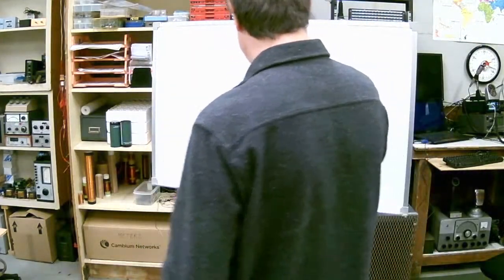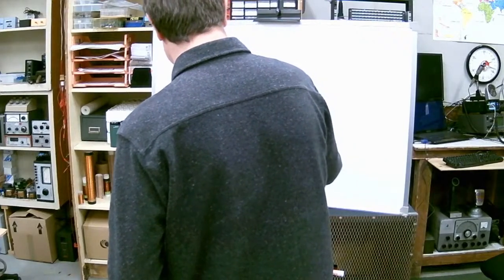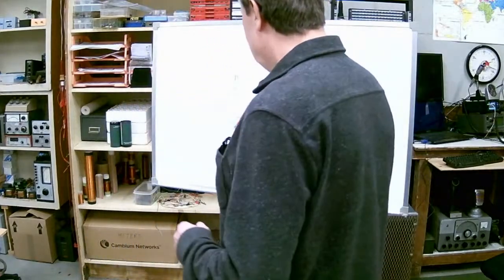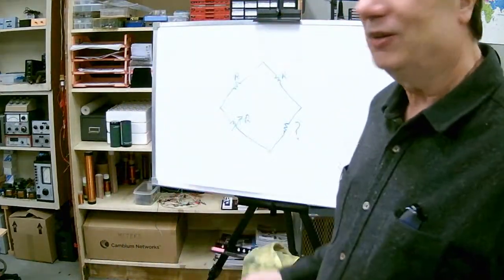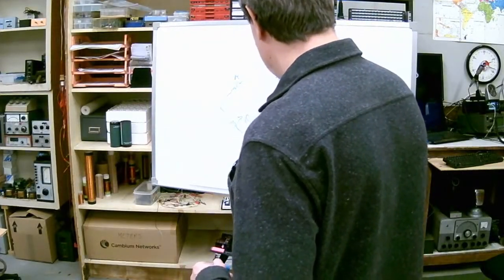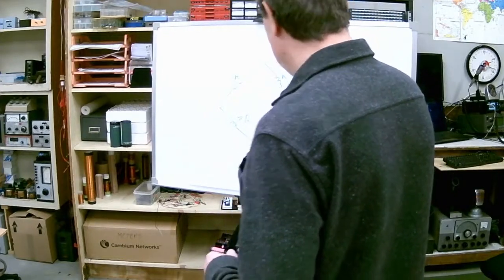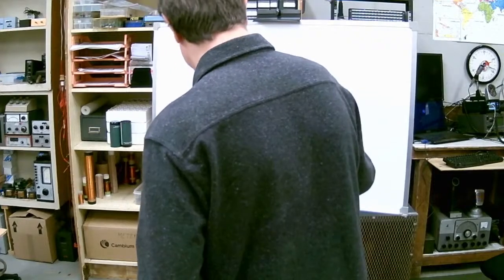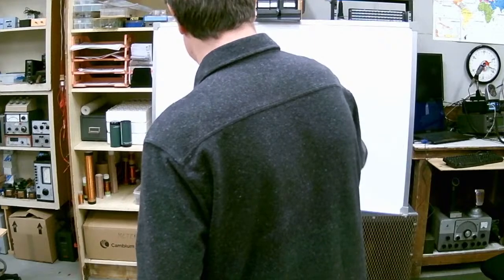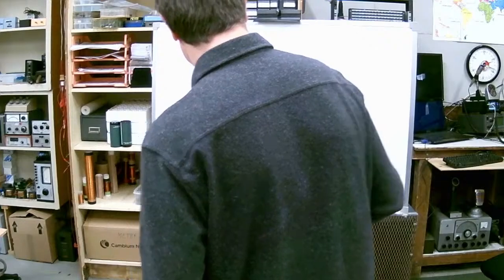Well, what we can do here is, this is variable, and this has a dial on it that tells you what the resistance is. And our unknown is some antenna. We'll connect that to an antenna here. We put a signal generator in here. Then we have a null detector here, basically just a galvanometer that tells you when you have current flowing or not.